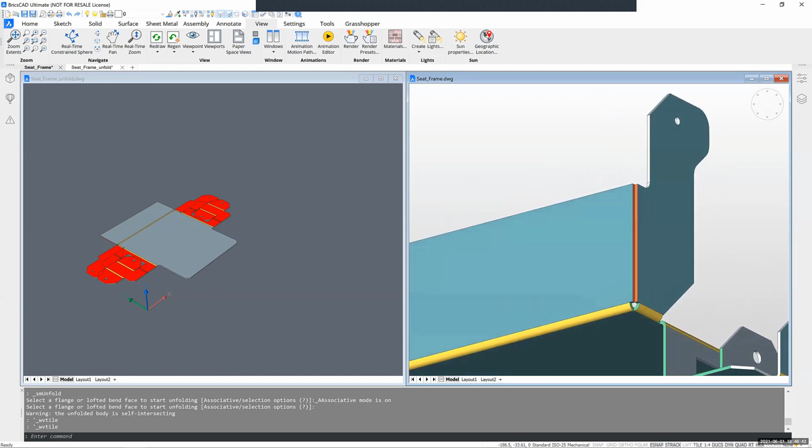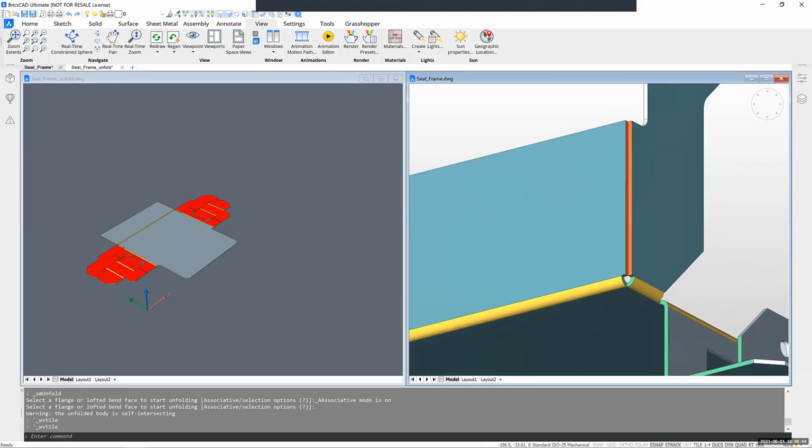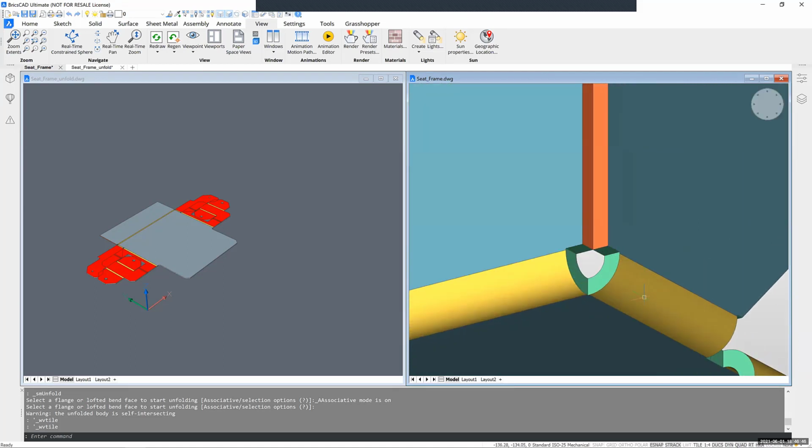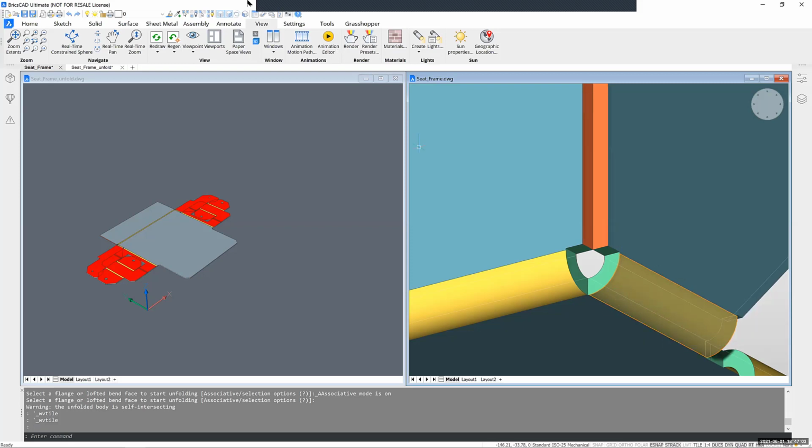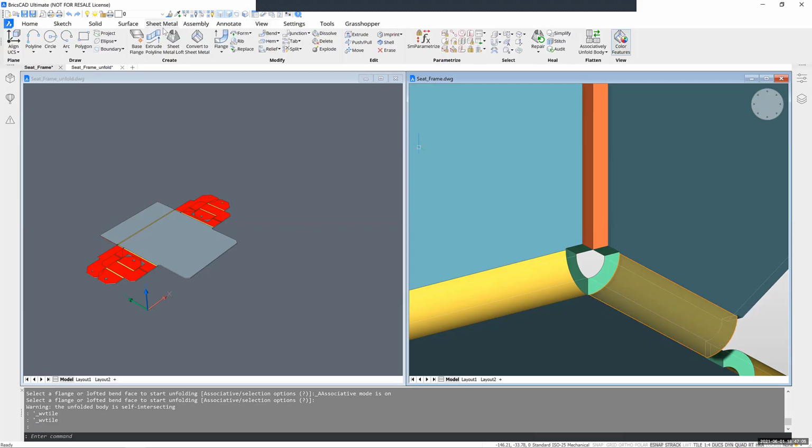So first of all, we will change the bend here. You can highlight a face, and then you can switch it to a junction. It should appear in your quad at your cursor. It's also under the sheet metal sub-tab of the quad, create junction. But if you wouldn't see it appear, you can also click the face and go back to the sheet metal tab.